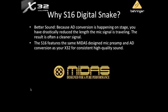So all of your mics on stage are going to be 10, 20, maybe 25 feet away from your stage box. Your super low mic level signal hits the mic preamp about 25 feet away, and then it's being preamped, and your A to D conversion is also inside of that stage box. So at that point, you're going digital down your entire snake line.